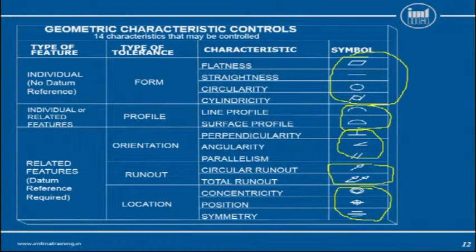Form group of parameters, they do not require any datum references, they are applicable for individual features available in the part, whereas the last 3 groups coming under orientation, location and run out, they require datums in a compulsory manner.